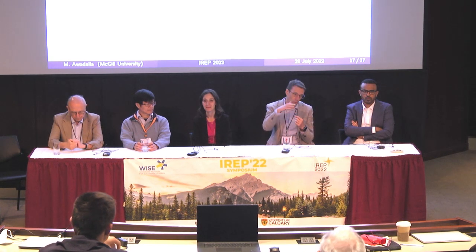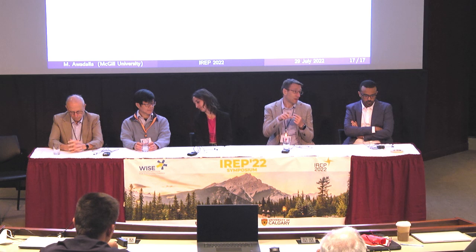In the figure I showed, not sure if you noticed, there's no coal generation left. So it's only wind and solar, and there are actually a couple of gas turbines that need to run to provide inertia. And the connection to Victoria is quite weak. So in South Australia, that's not too big of an issue. NEM-wide, it is. Especially in Queensland, it happens quite often, even now, when the prices in the morning or during the night can go over, I don't know, even a few thousand dollars per megawatt hour. During the day, prices can be negative, because there's so much solar.